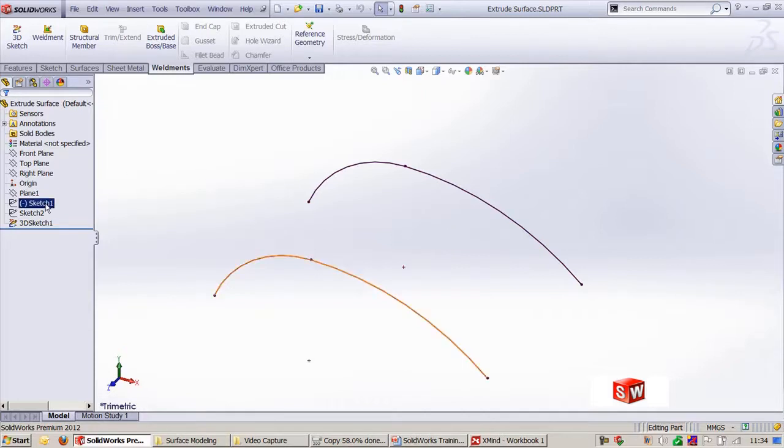Now you understood. Now we will understand how the sketch has been created. I created a 2D sketch and one more 2D sketch, and using a 3D sketch I converted this 2D sketch using convert entities. Using that command I made one more copy of this. Now this sketch is inactive and these two are in hidden condition.